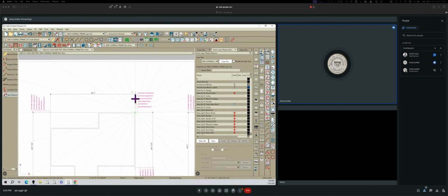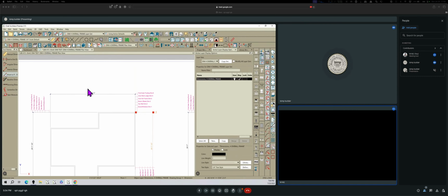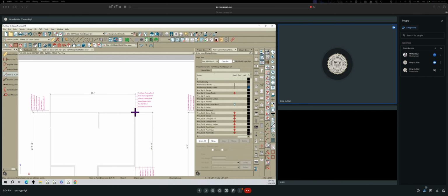This thing does not want to click snap where you want it. Just do a point-to-point dimension, and then you can. That's what I'm gonna do, because that'll work. It'll snap to whatever you want. Well, that's a block, though, right? You created a block for those texts. Yeah, that's a block. You'd have to unblock it. Point to point is not gonna want to do it. Yeah, you're gonna have to unblock it.